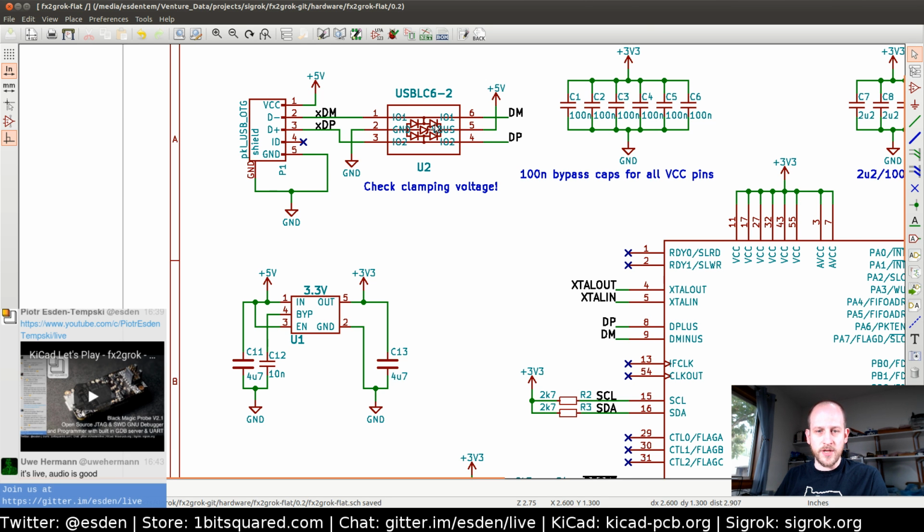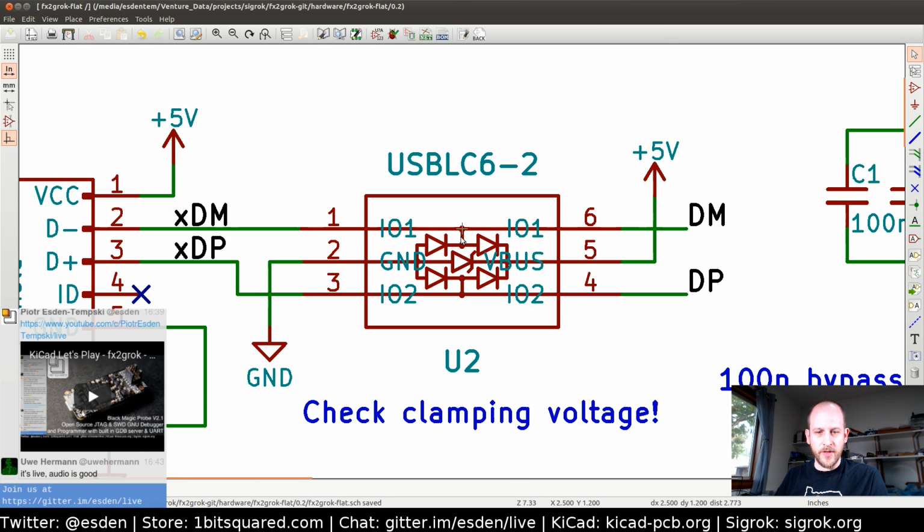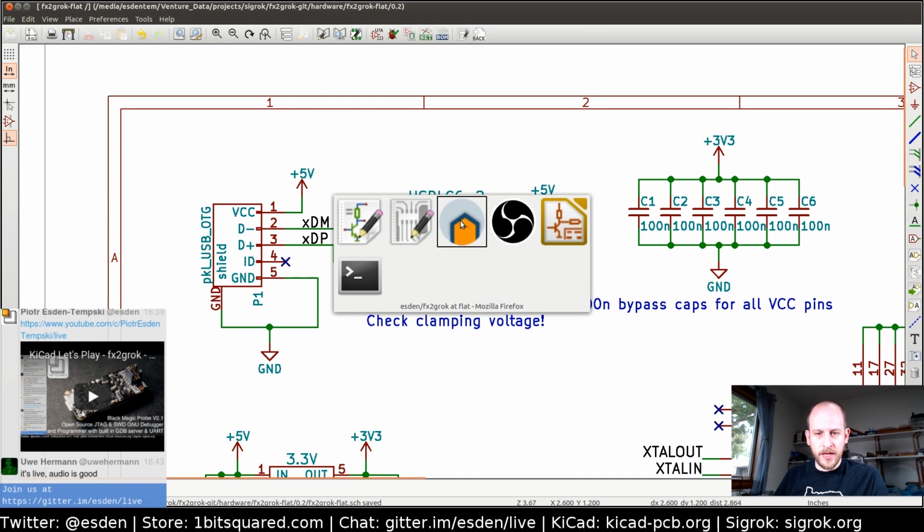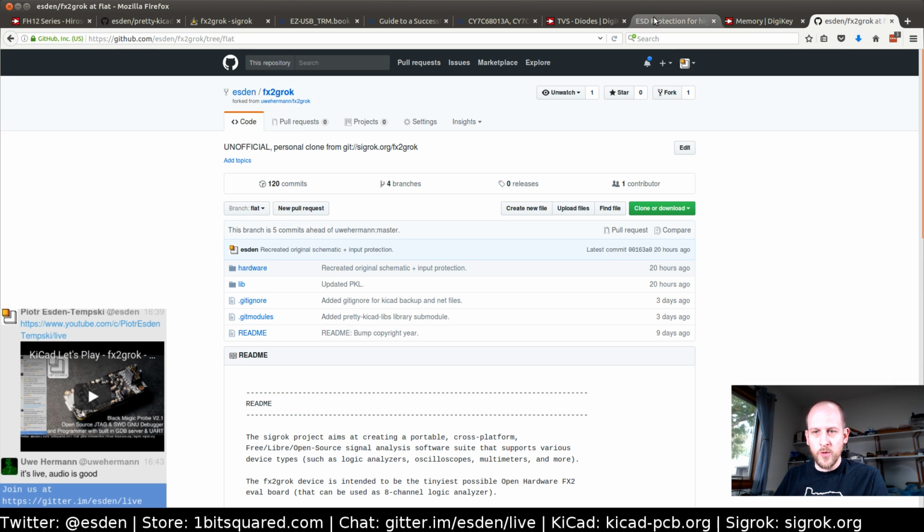The other diodes are there to clamp it so that the voltage doesn't go below 0 and not above 5 volts, and it conducts and it shunts it here, even if it is below the 6 volts reverse, so the Zener voltage of the middle diode. So that's that. We can look it up in the datasheet. These things are always listed.